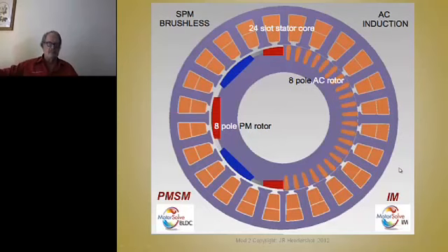I just wanted to make that point to give you a feel for the difference between slip or imaginary moving poles, because we're going to find out later that slippage varies with torque, the load on the machine, and that's why the induction machine has such a poor torque speed curve, not a very useful one, when it's driven by constant frequency and voltage without being able to control the magnetizing current separately. We're going to study the magic of that later. So that concludes this lecture.